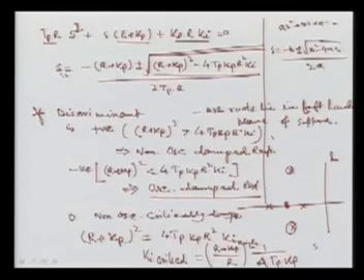To see the performance, subcritical values are normally required. If Ki is less than Ki critical, what will happen? This is the critical value when the discriminant is 0. If Ki is less, this will be positive, and then we get the non-oscillatory damped response. If Ki increases further, it is going to be negative. Once this is negative, we will get oscillatory. If it is positive and more than that, what will happen?